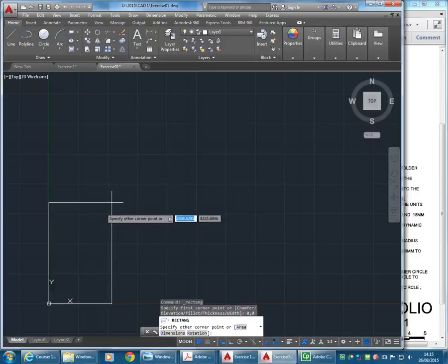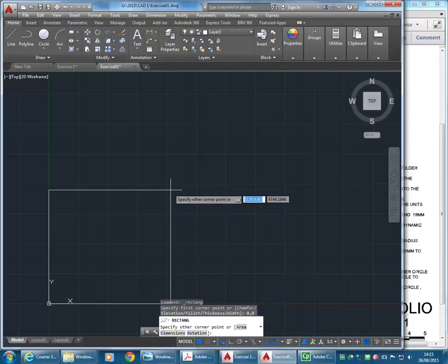enter, and that will start on the origin. It's always a good place to start your page on the origin of your file. And then, do you remember the size of the rectangle you did in the geometry exercise? Yeah, 297,00, that's right. So that's a good one to remember. That's the width of an A4 page times 100. And then, so I've done that, and now I'm going to press comma and give the second size exactly 210,00 again. And that's again A4 dimension the other way.